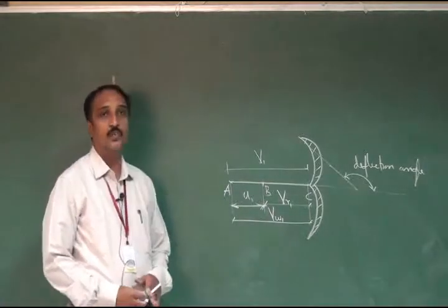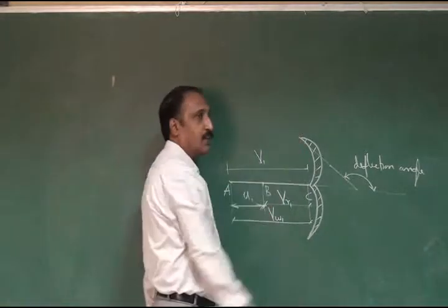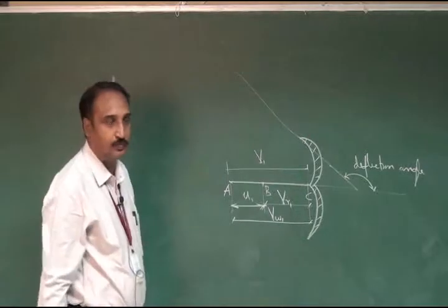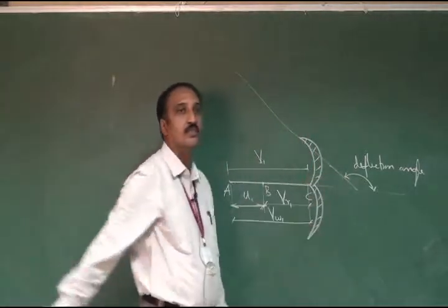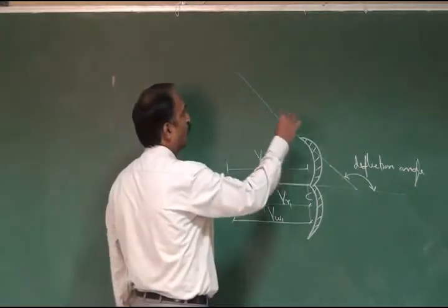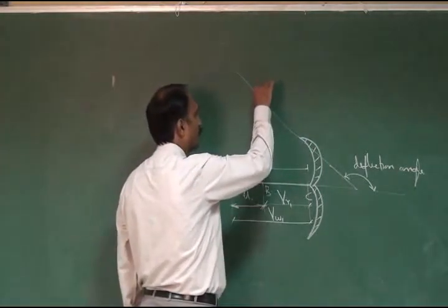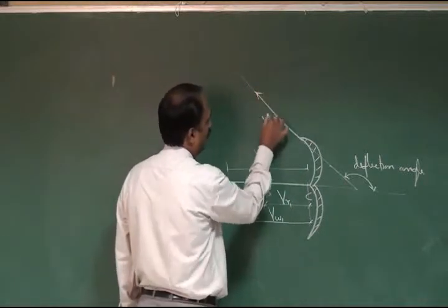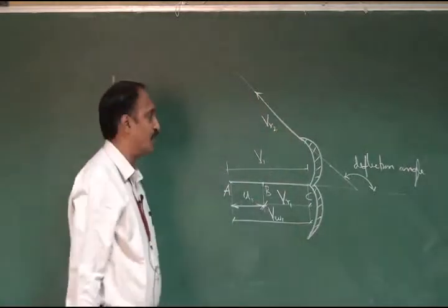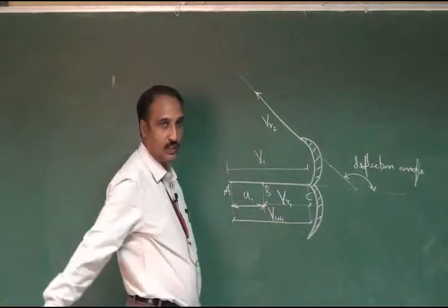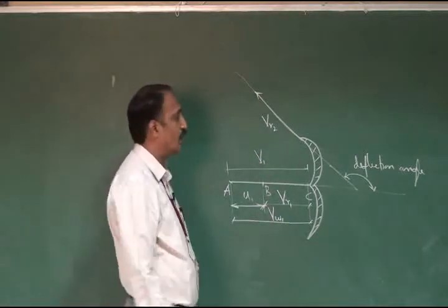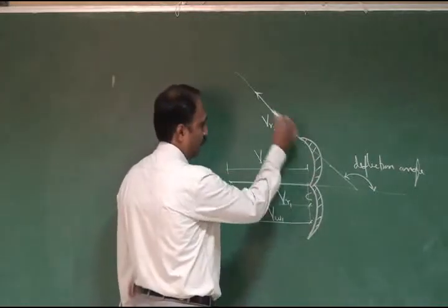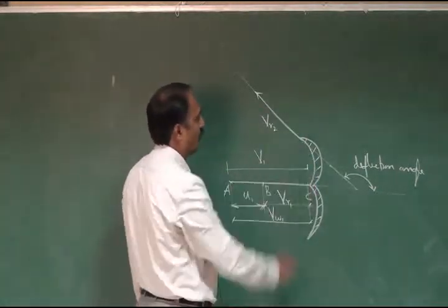So in order to construct the outlet velocity triangle at the outer tip of the bucket, consider this slope with respect to deflection angle of the bucket. Now along this slope you have to draw the outlet relative velocity vector VR2, such that VR2 is equal to VR1, assuming the no energy loss condition when the water flows through this bucket.